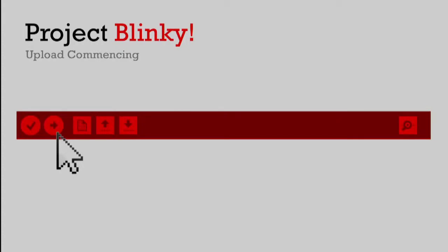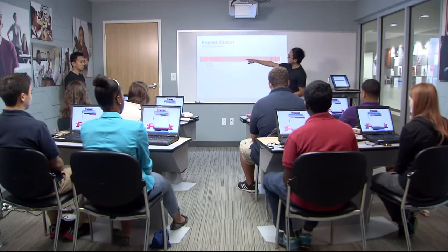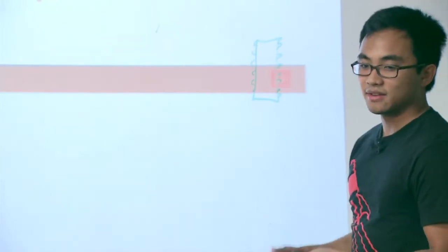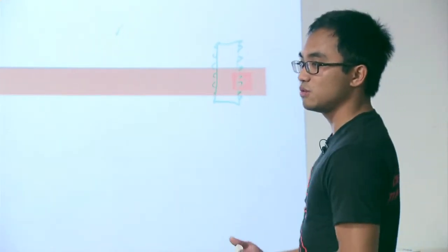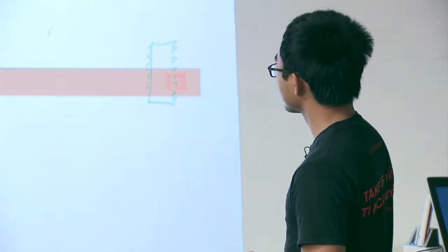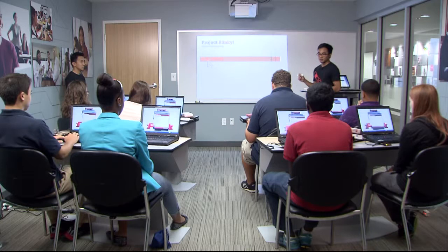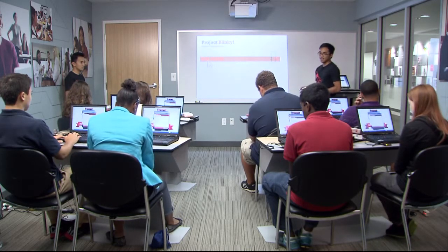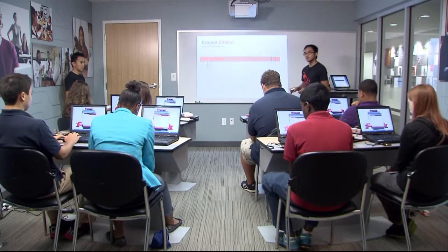And then suddenly the microcontroller is going to do exactly what that program told it to. So go ahead and click that button, and you should see a couple of things happening on the computer. But by the end of it, your LaunchPad will have the new firmware, the new software that you downloaded to the microcontroller. And then keep an eye on the LaunchPad, because once you do that, the code will immediately start running. And make sure that that green LED blinks only 10 times, because that's what we told it to do.